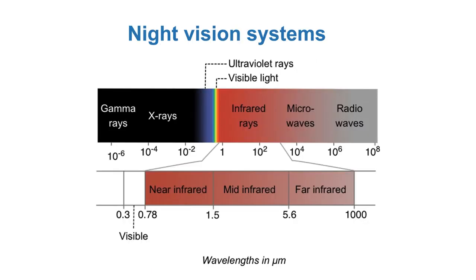In addition to the vision sensors I have discussed so far, there are specific techniques and technologies that enable better camera performance at nighttime. There are two main types of night vision cameras, near-infrared and far-infrared cameras, or rather, sensor systems. Fundamentally, they work on different parts of the spectrum of electromagnetic waves. A main difference is that the near-infrared is active and the far-infrared is passive. That is, for near-infrared or NIR, there is an active illumination of the scene in front of the vehicle. A main reason why the standard main beams of a car are not sufficient at nighttime is that it's not acceptable to glare oncoming traffic.